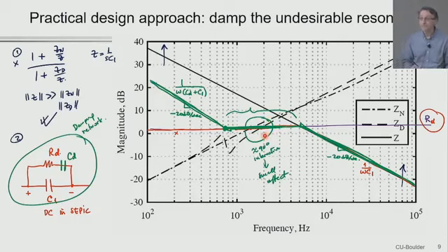Okay. So you can also place it above the dot, right? Then the Q factor just becomes equal to the value of RD. So again, there is room here for playing with these components, and you can move this up and say, I'm just going to cross right here exactly and see what happens, right? So it is a matter of what we would call optimum damping. Leave that question for a little bit later when we do the input filter design. We'll actually address this in significant detail. There are closed form expressions for how to do the damping in the optimum sense. But right now, let's leave it as something that you can play with a little bit.